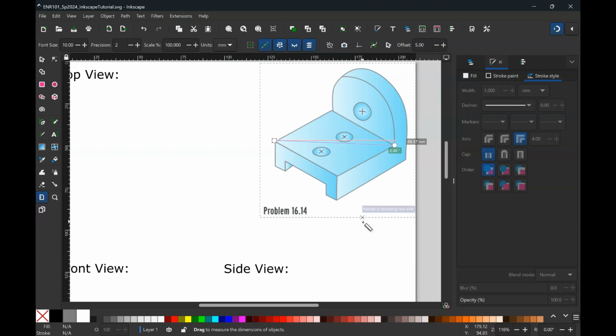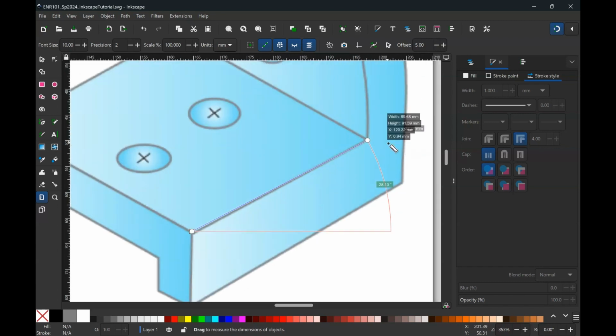You'll do some math and you'll realize that that means each of these sides of the seat of this chair-shaped bracket should be about 50 millimeters or so. You can also measure some other features. So I would say that if one side length in this perspective is about 37, I can also get the size of the back of this chair as well.